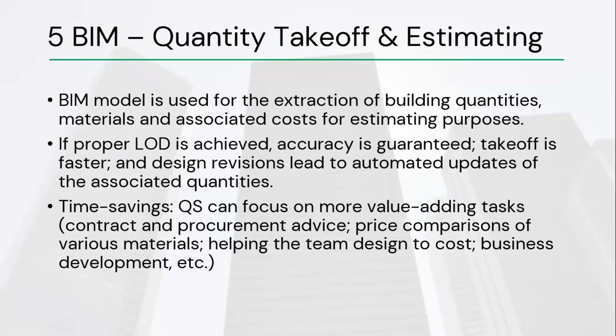And this level of development, we talked about it sometime earlier, is an agreement that says at this stage of the project, this is the participant who will be the biggest consumer of the information that is being produced. And these are their information needs. So when we are creating these models, we need to put the information that is required for these people to use this information to make decisions. In this case, for the QS to make decisions on cost and advise the client and the rest of the team.